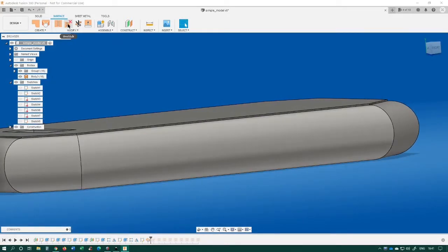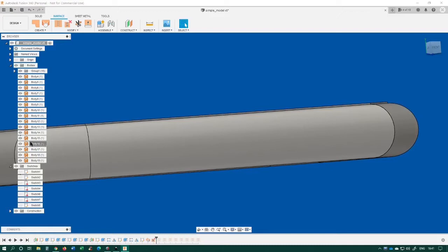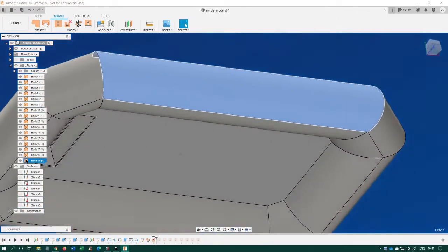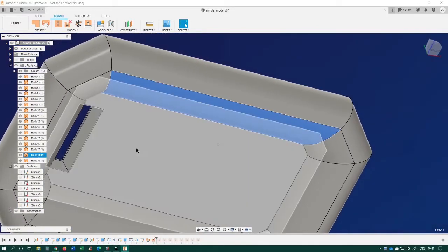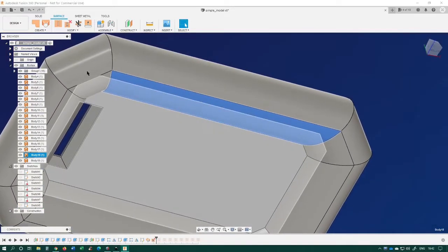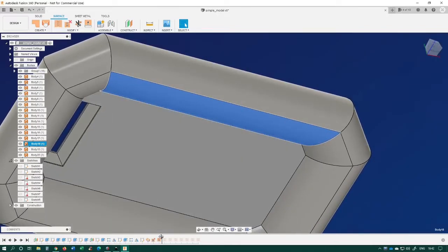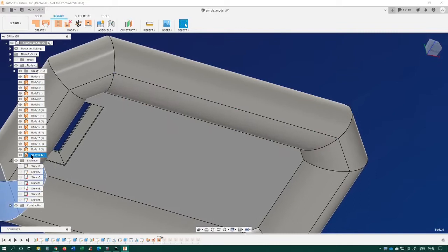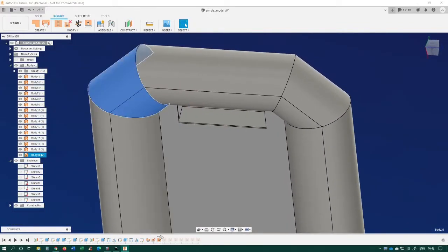This is no good for the next step, so first we need to unstitch the surface. Use the Unstitch tool and select the surface. Once you've done this, you'll notice that each section is in two parts. We need the sections to be a single surface, so we need to restitch the parts for each section. Go ahead and use the Stitch tool, selecting each pair of surfaces per section. Once done, you should have the same number of surfaces as the hull has sides.